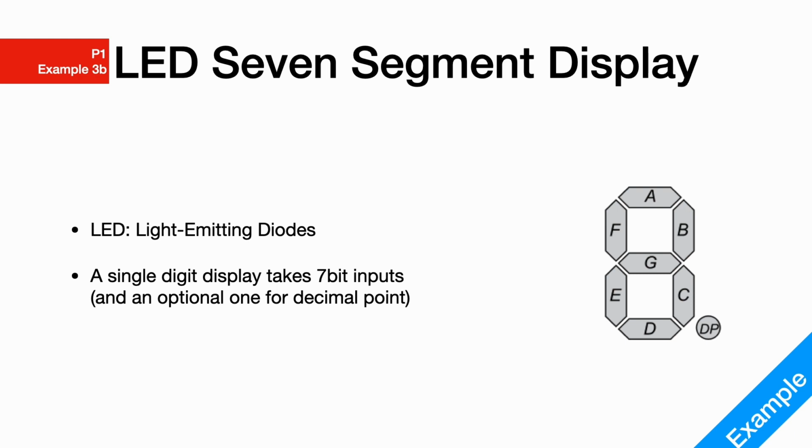You have different LEDs, LED A, LED B, LED C, D, E, F, G, as well as a decimal point. By lighting up different strips of these LEDs, you'll be able to display certain numbers. Now, it is specified in the international standard ISO organization that a 7-segment display should always be arranged in this particular order. Namely, the 7 segments are displayed as follows. You have segment A, B, C, D, E, F, G, always in this precise order, as well as the decimal point, which is optional.